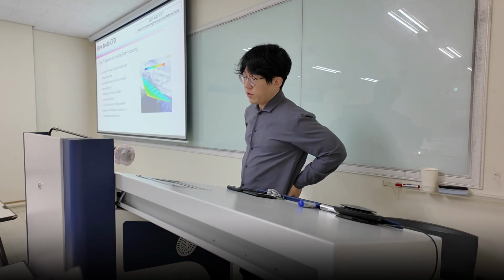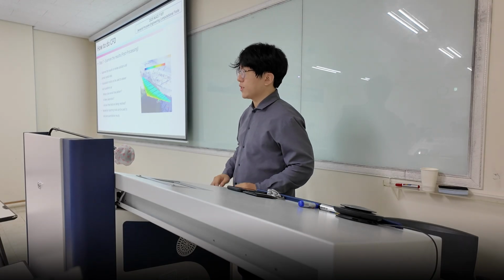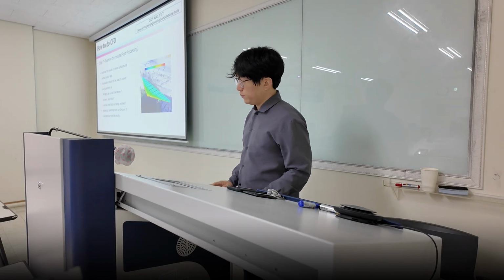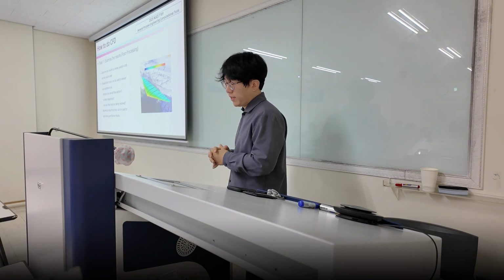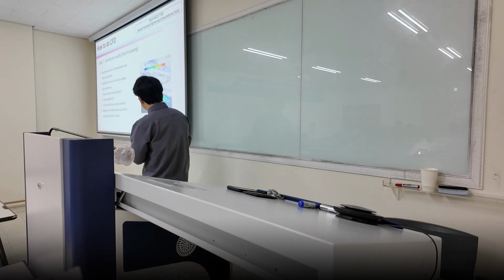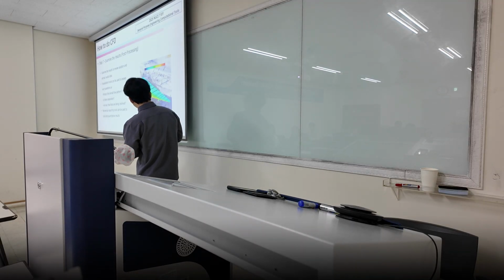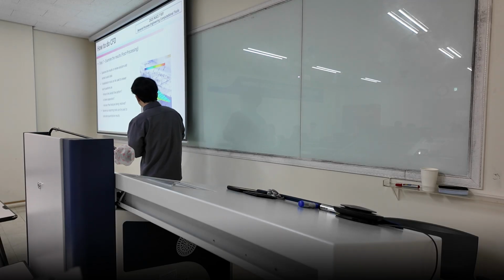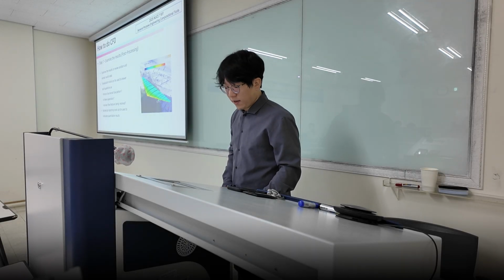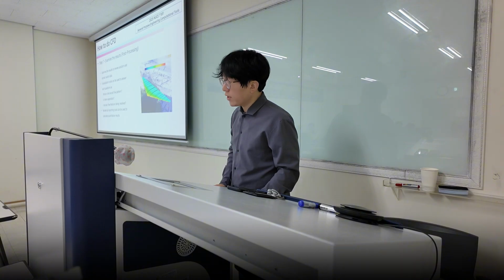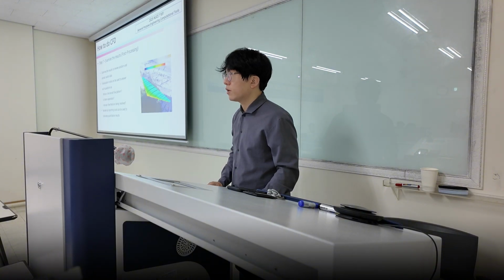So after running the solver, you're gonna run what's called post-processing. So you're gonna color them, you're gonna overlay them with other geometry, so you can have a nice picture as a background. So this will also help readers to understand what you're doing, and make sure you're using a proper visualization approach to display your data.